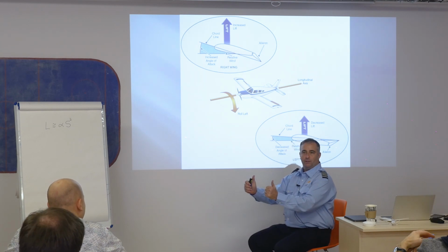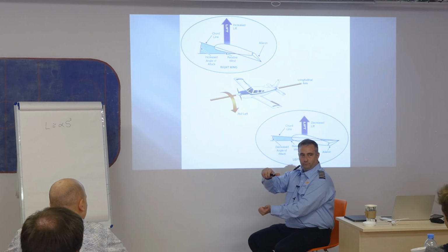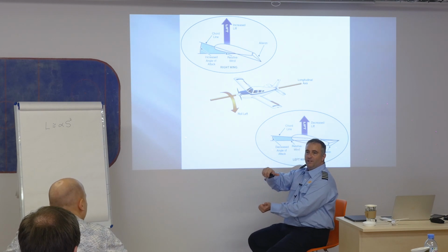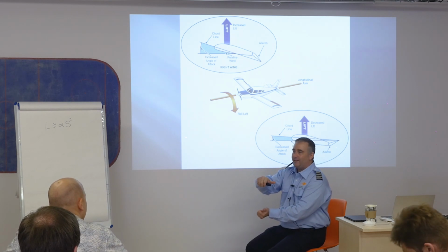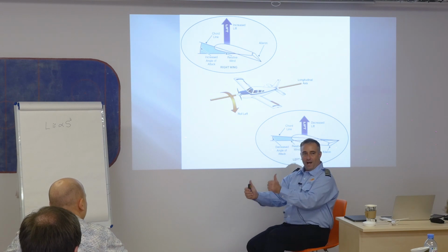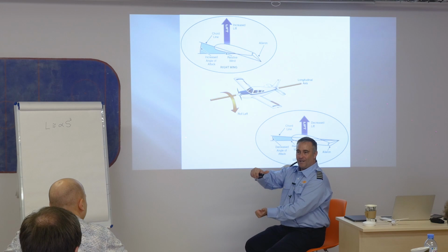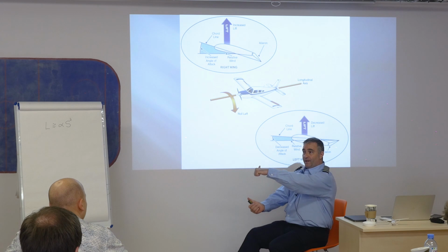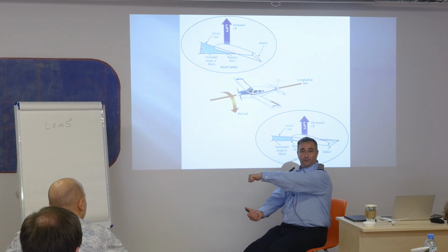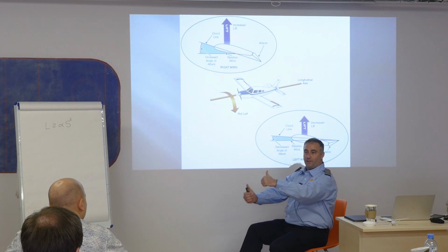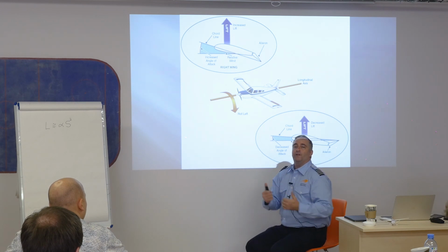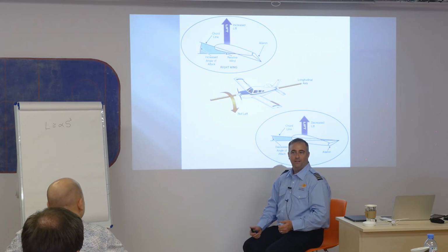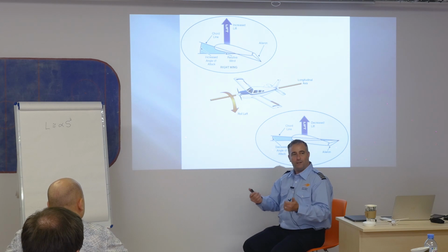So if I push left aileron, what should I do? It won't do it by itself. Okay? It won't do it by itself, I can guarantee you. So you have to push a little bit of left aileron as well. The same thing if I do it to the right. If I go to the right, I got to have that right aileron, right rudder. When I release one, what am I doing? Releasing the other. So when they say coordinated controls, we understand what coordinated means. Okay. That just means using two things together at the same time.